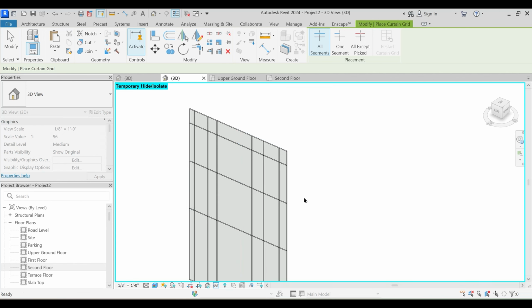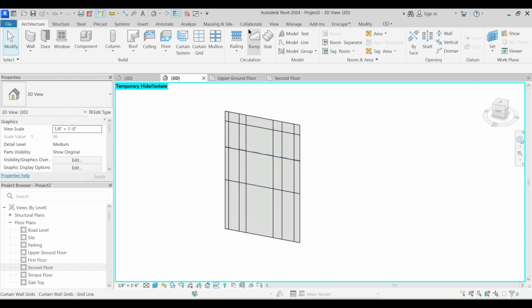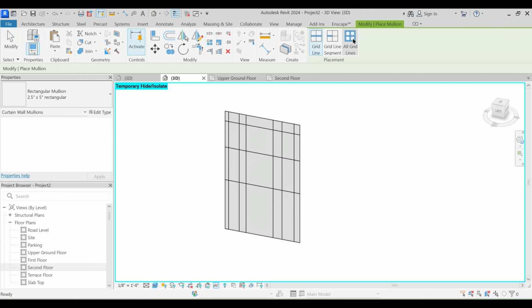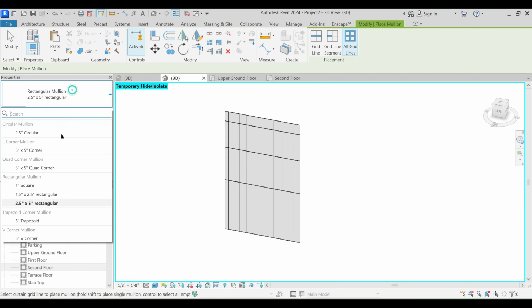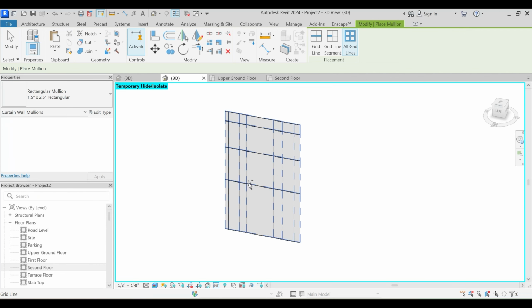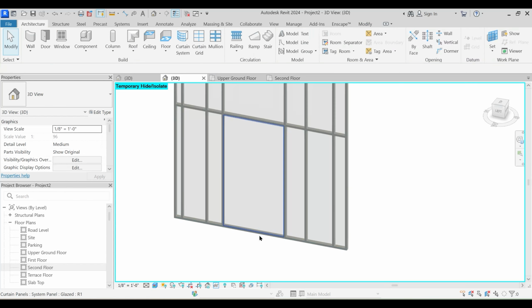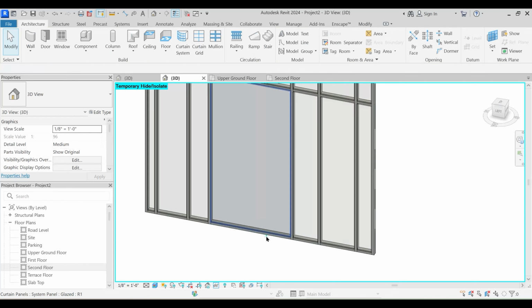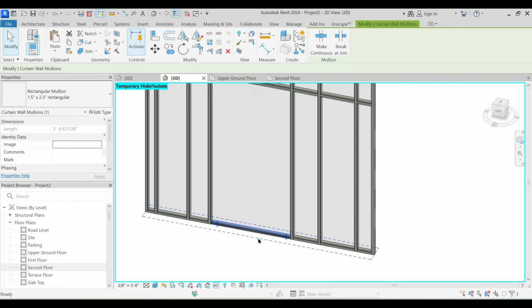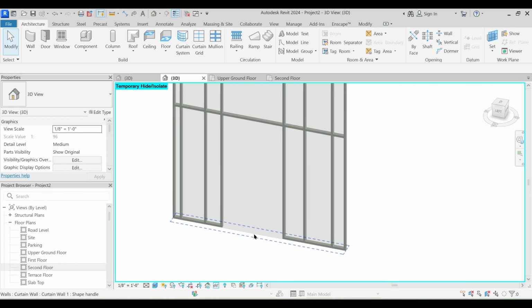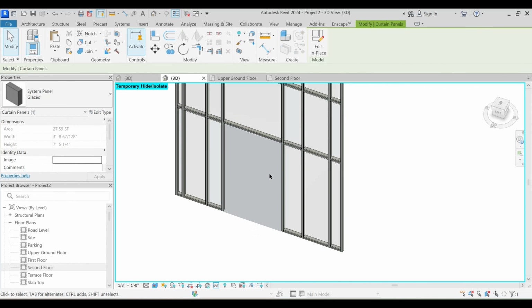That's enough. Okay, fine. With this, I'll say that mullions and all grids, and I will select this lower size and just snap. Okay, and I'll just press tab until I find this mullion. Oh, you don't need to press tab to select the mullion, but you need to use tab to select this. Okay, this particular panel.